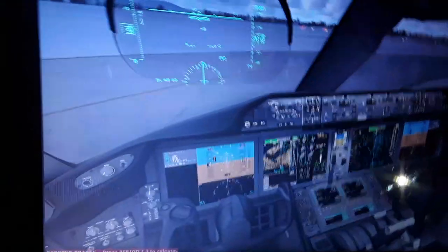We have the altitude indicator, as I told you, the pitch in degrees, the bank angle, and the artificial horizon. Also the ILS localizer, we have the horizontal localizer and the vertical glide slope displayed from the onboard aircraft receivers that receive the radio frequencies transmitted from the runway threshold antennas of the ILS, the instrument landing system, which transmits radio frequency from the radio transmitters and receives on the onboard antennas of the aircraft, and displays the horizontal localizer and the vertical glide slope. You can see here in the primary flight display.